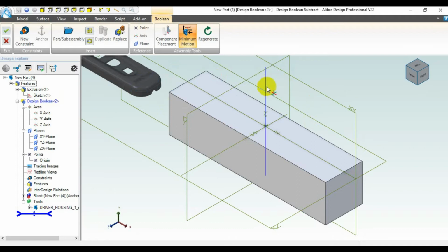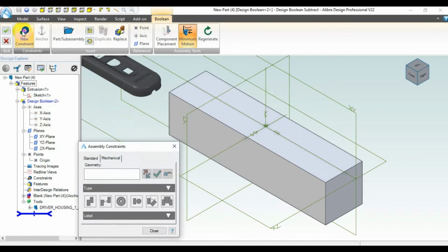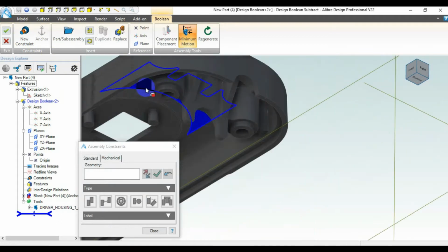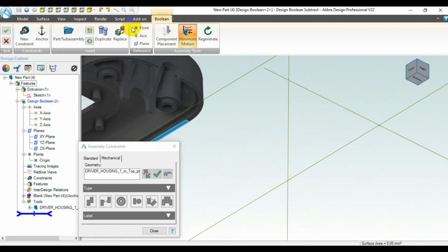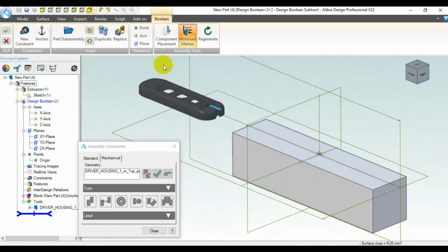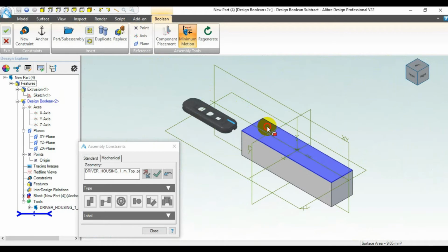Now I could put this in a solid block, this block going up here, but that's not really going to help us because it doesn't create a moldable thing that would work in an injection mold. So we're just going to immerse this in here like in a tub of water, and see if we can get this to work. So there's my part imported there. We'll need to basically shift this thing around here. We'll flip this over, and I'll select this bottom part here. That's where the mold is going to separate, this face down here. So we'll select this particular face here, and go back into isometric, and we'll click that face there.